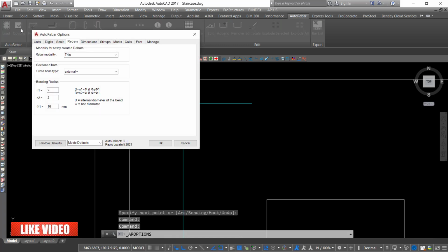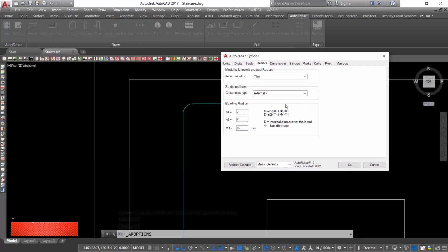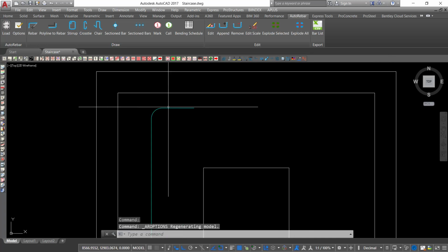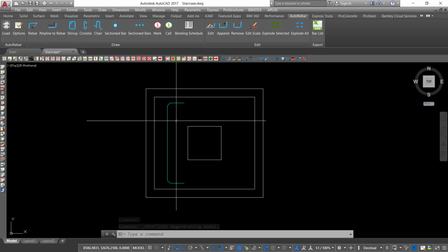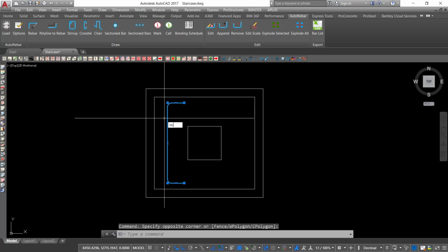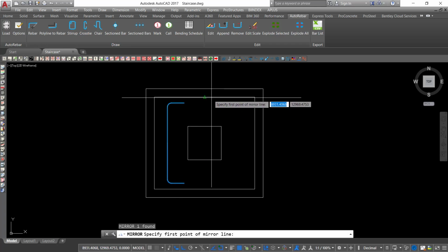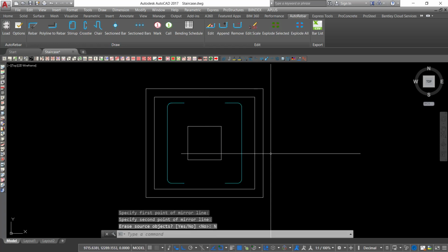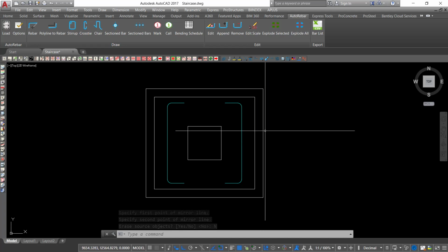You can click on that end and come to rebars, and you can adjust the bending angle of these bars. I can take it to 4, but 4 would be so much big. So if I type 4 there and click OK, it will be able to adjust itself, but we can leave it on the same spot. So what do we do once we've created this? We'll just select on this, type MI on your keyboard and enter, and pick a mirror line here, and we'll mirror that on that end and click no. That's how it's done. Now we've created the vertical bars.